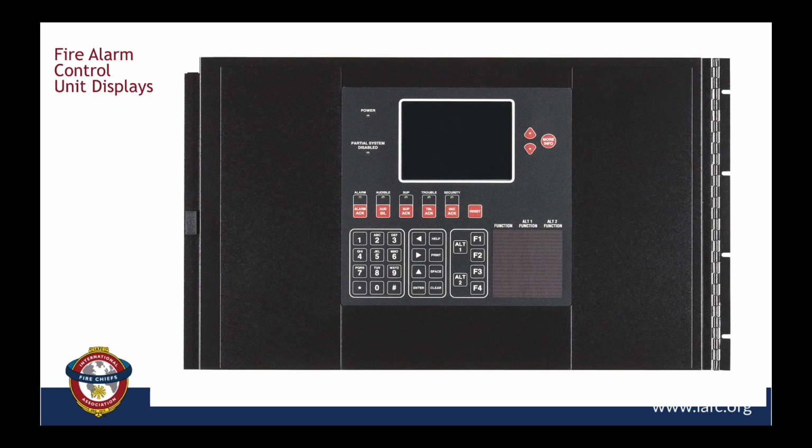This particular panel also has a function of being able to monitor security devices. So door contacts, card access alarms, things of that nature are within the listings of this system to be able to bring those components into here. Those devices should never call the fire department, of course. Those are designated for owner's use or to go to the police department. But you can see that this is allowed to also bring in security on this panel.